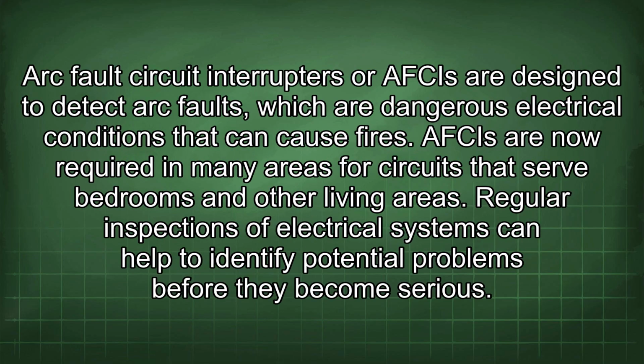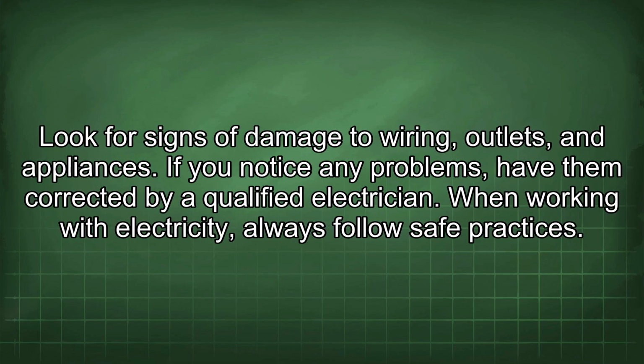Arc fault circuit interrupters, or AFCIs, are designed to detect arc faults, which are dangerous electrical conditions that can cause fires. AFCIs are now required in many areas for circuits that serve bedrooms and other living areas. Regular inspections of electrical systems can help to identify potential problems before they become serious. Look for signs of damage to wiring, outlets, and appliances. If you notice any problems, have them corrected by a qualified electrician.